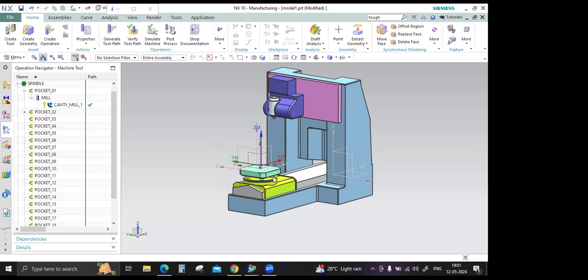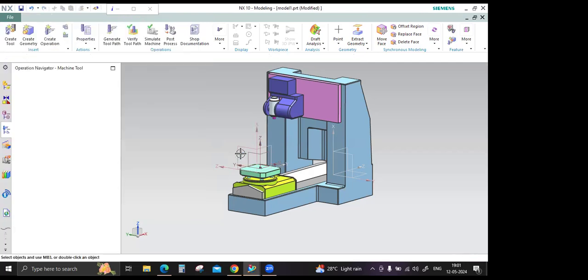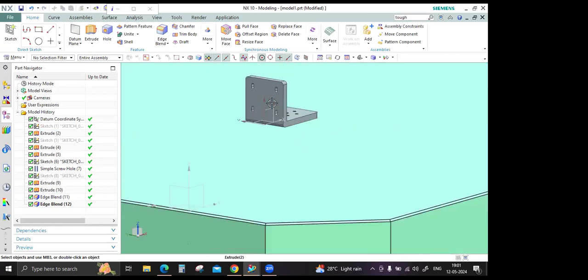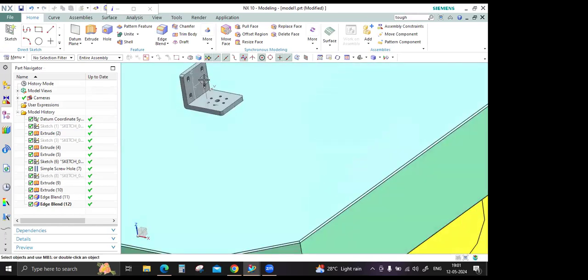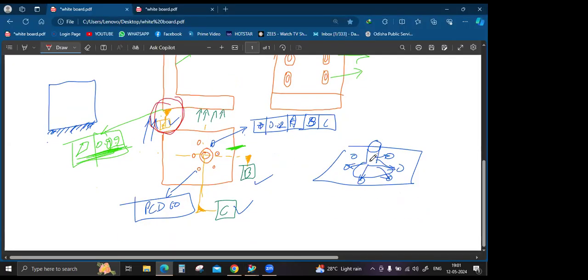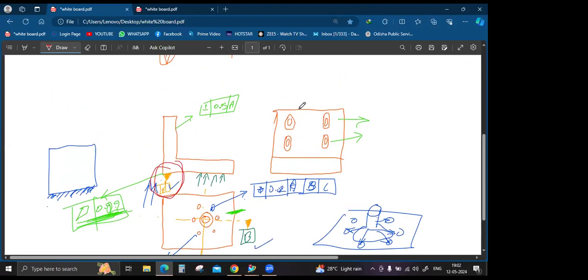But guys, for the industry, you people have to remember one thing, that is, sir, what are the dependencies present over here? As I have told, there are dependencies over this particular shaft and its mounting holes. And to adjust that, we may have to provide some slots over here. That is why we are providing the slots on the clearance hole, not on the tapping holes. So where we are having independency, where we are dependent, where it should be tightened, everything we have to see.